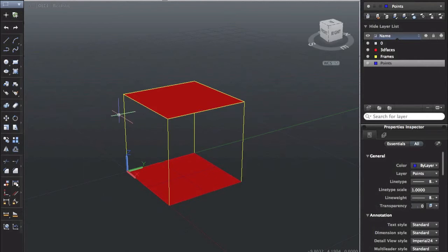One more thing that's very important to remember. You always need to remember where your Z direction is. By Z direction, I mean the direction that is up. That direction may be Y or X depending on how you decide to orient your model axes. In this case it is Z, so you just need to remember which way is up and the units that you're using. Let's move on to the small machine that I've got right next to me at the moment and run the simulation on SAP2000.